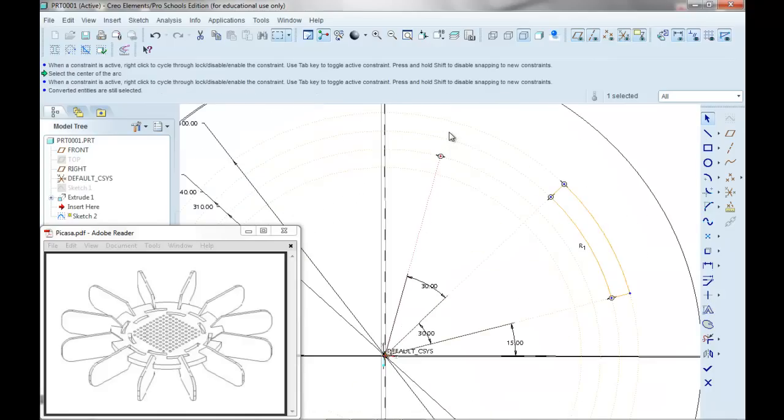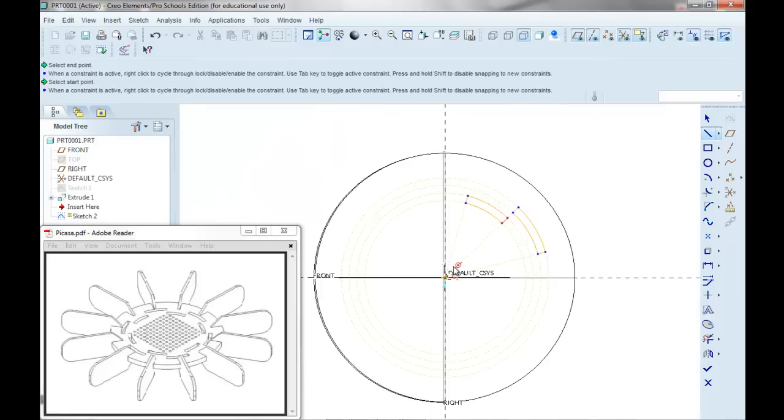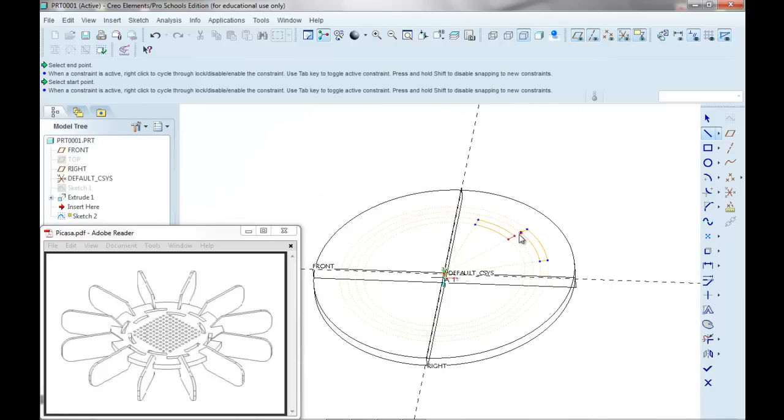Let's get back in here so we can see a bit better. So now I'm going to select the arc again, select the middle, and select this part and that part. Select the center of the circle again, and coming out here, creating those two. And now we'll go to my line, and middle mouse click, and still in the line command, click and click, and middle mouse click. So what I've done now is I have two areas that are going to be utilized for my slots.